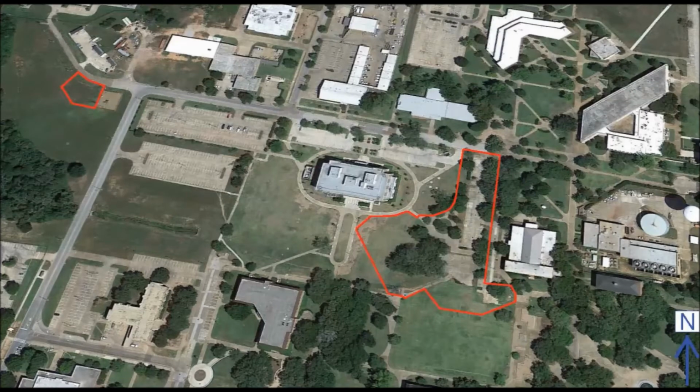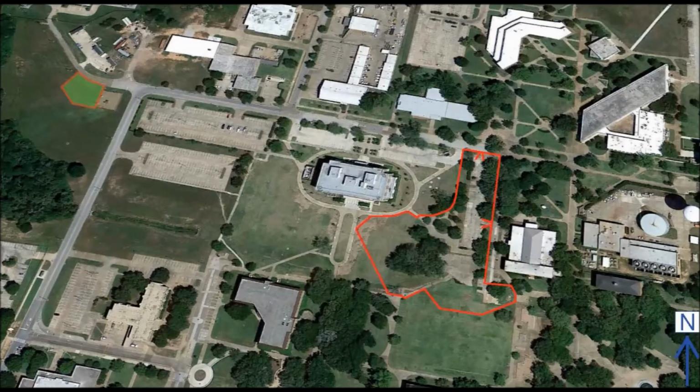Construction fencing, shown in red, will surround the construction areas. Gates will be located at the north and east sides of the construction site. There will be a guard at the north gate during construction hours to prevent unauthorized visitors from entering the site. The east gate will remain closed with exceptions for deliveries or other access needs. The secondary laydown area, shown in green, will be located off-site to the west down Ann Preston Street and will be used for contractor parking.